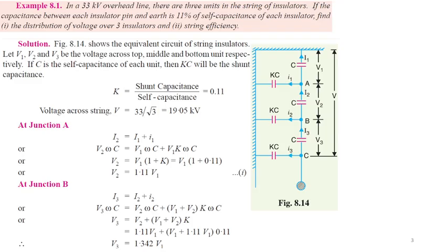So the voltage is not evenly distributed across the disks. Each of these voltages is completely different. Instead, the disk closest to the conductor experiences the highest voltage stress.